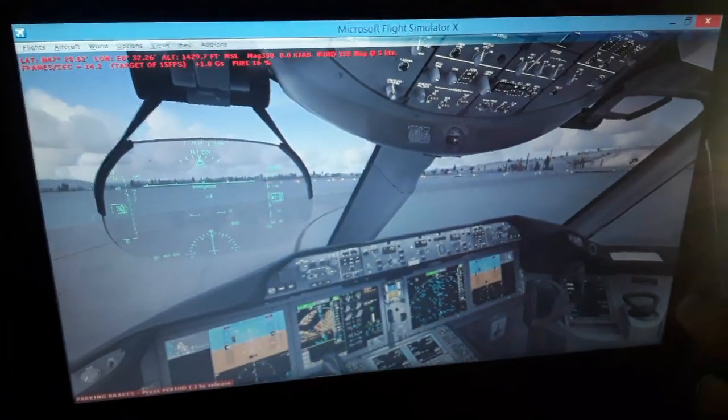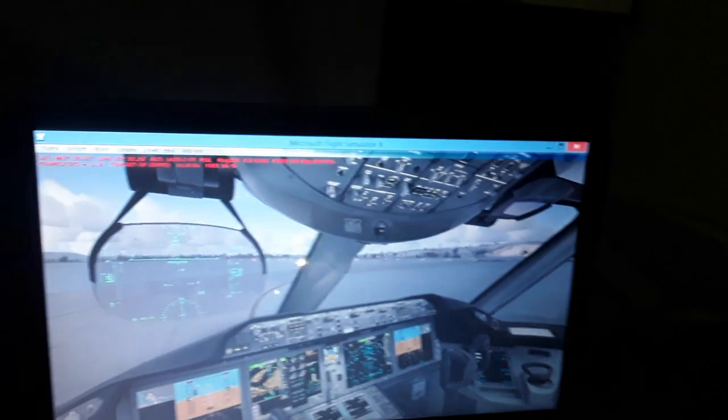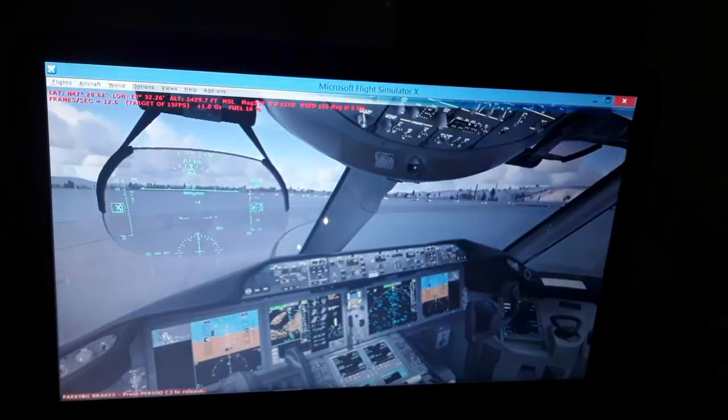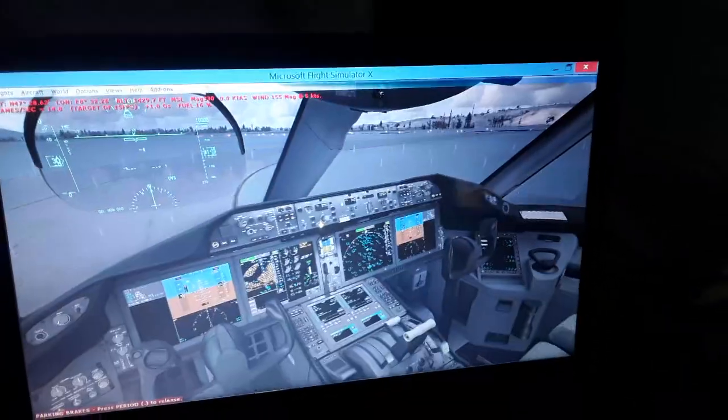We have also the ILS localizer crossbars displayed in the primary flight display. We have to tune a unique radio frequency each time we take off and we land from a different runway and airport, for a given runway heading, for the ILS localizer to be aligned both horizontally and vertically. So we can tune this either manually from the radio management panel or selected from the flight management computer when we create the flight plan later. I'm gonna show you how to use this planner, the flight plan, to create a flight plan and also select the ILS localizer for approach and landing.